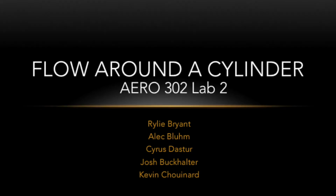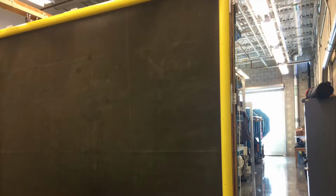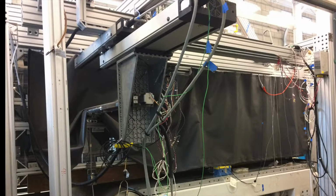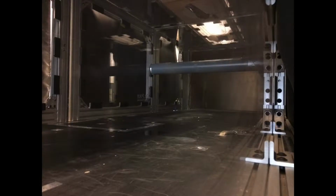For this lab, we used the Cal Poly low-speed wind tunnel to analyze different types of flow over a cylinder. We determined the pressure drag coefficient using discrete pressure measurements taken on the surface of the cylinder and evaluated the effect of changing the Reynolds number as well as the surface roughness. The goal was to see if we could reduce drag by adding strips of sandpaper at the point of flow separation to trip the flow into turbulence and stay attached longer.